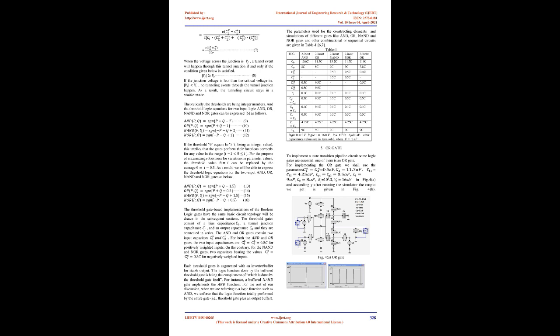Coulomb blockade works against the steady flow of current because as soon as the high voltage, logic 1, is applied to the input, it causes a shift in the induced charge on each of the islands of the two SETs by a fraction of the charge of an electron and keeps SET1 in Coulomb blockade and SET2 in conducting mode. Eventually, the output changes from high to low.